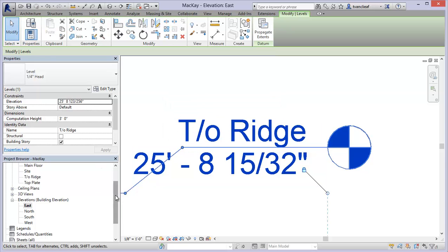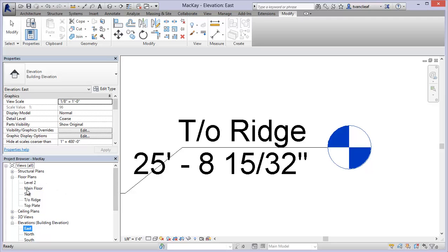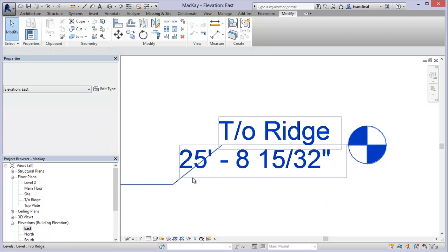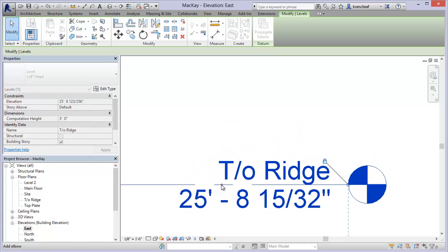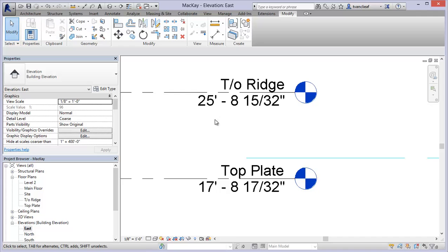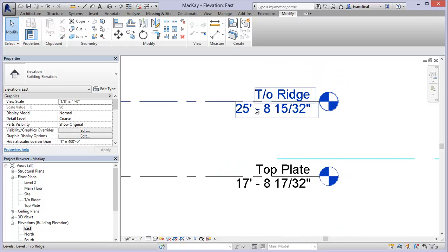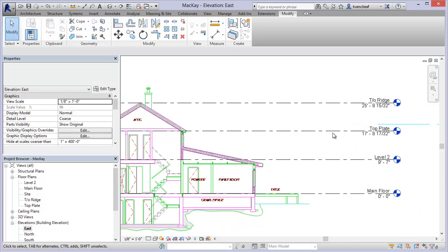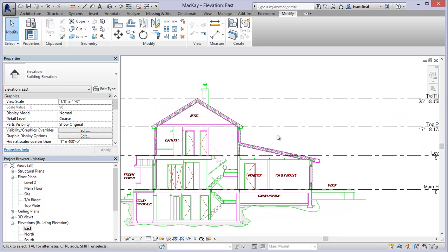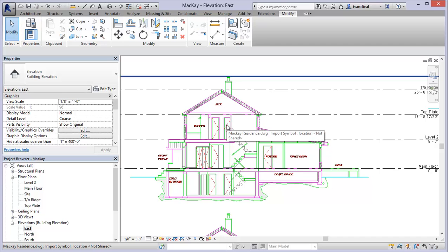This information is going to be a little bit better here in my project browser. It's going to tell me exactly what I need to know. Something I didn't cover was in here I've got this elbow from the last video. I don't need that now, it's moved, so I'm just going to drag the two nodes for that elbow until it's straight, and then the elbow collapses. Okay, so I'm going to go ahead and modify these labels appropriately. And then in the next video, we'll take a look at setting up some walls and getting the walls created.